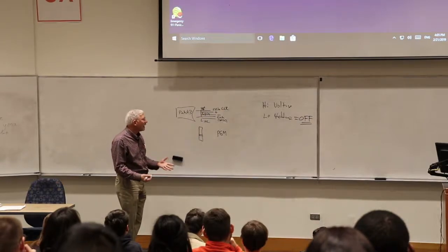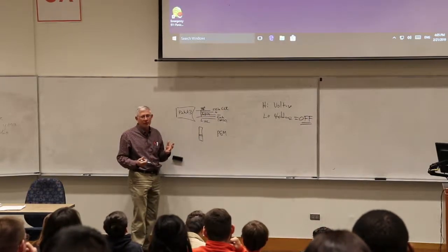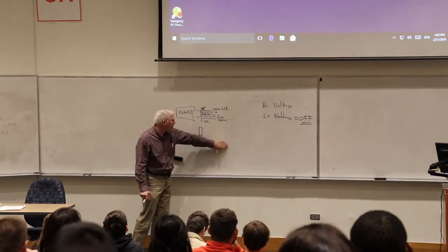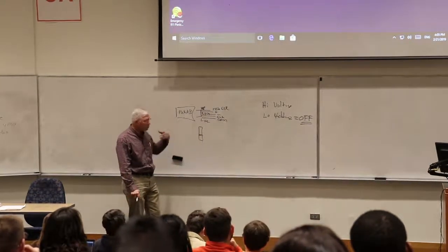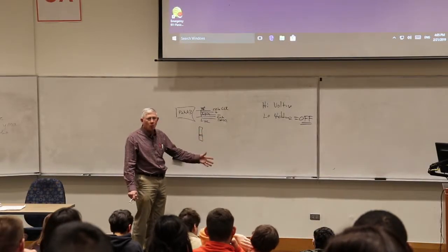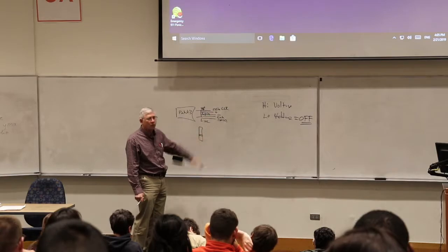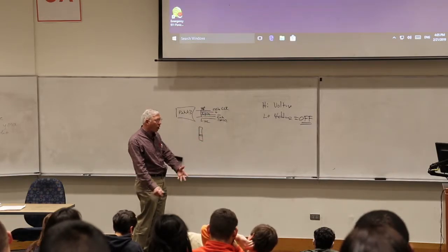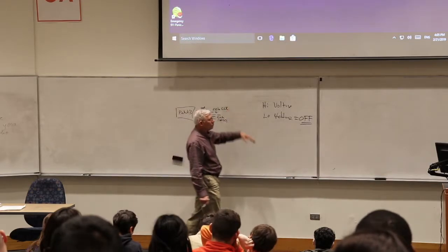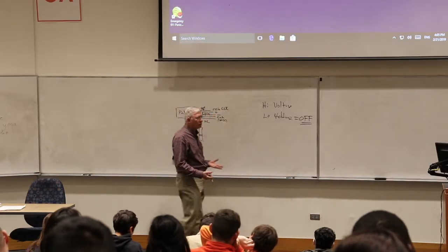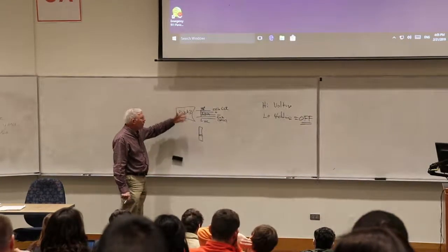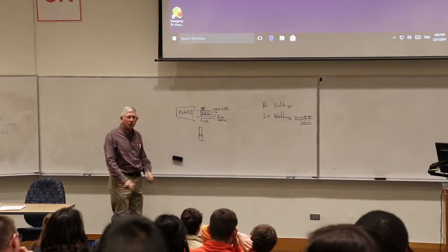Well, it turns out the Snap uses low voltage programming. It also turns out that when the programming pin was taken out of the processor line, so the new ones don't even have that pin, the problem of the chip locking up if you had the low voltage programming bit programmed for off went away. So now it's better to just program it for low voltage and do it in low voltage. There's really no problem with that. The PICkit can do either one, but the Snap can only program in low voltage.